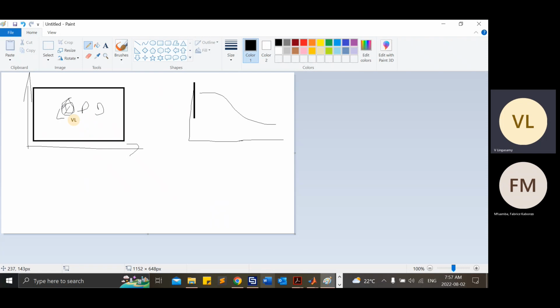For example, this particular unit cell, maybe in the S curve, is generating 220 degrees, and this particular unit cell size is generating 200 degrees, let's say. Whatever gets reflected will not be exactly 220 degrees, because we are not doing the practical simulation considering the surrounding elements. We are only following the Floquet port unit cell approach, where the unit cell is placed in the presence of same sized elements. That is Floquet port.